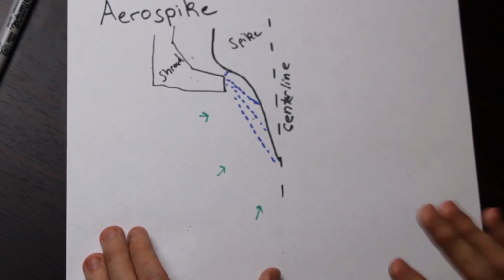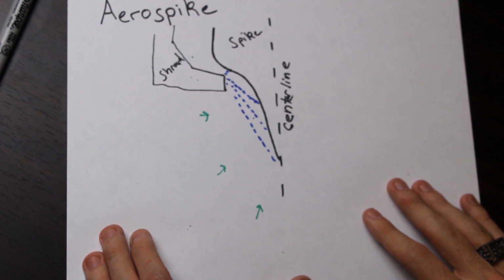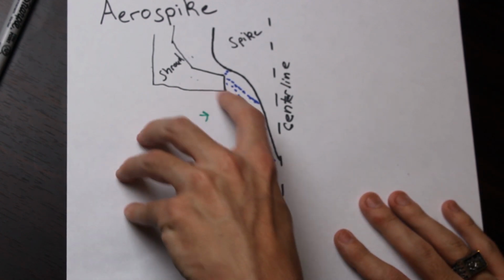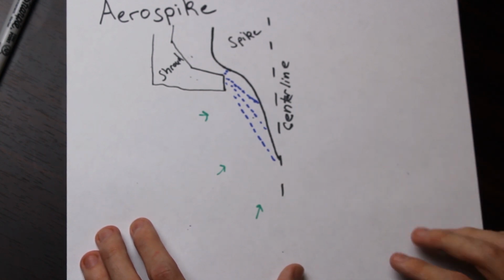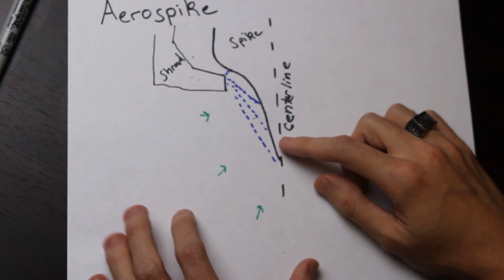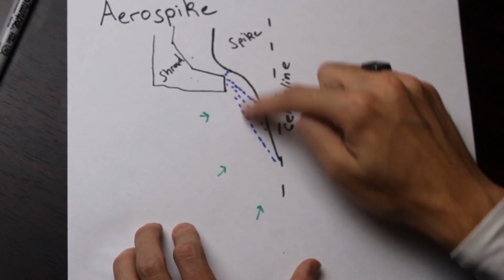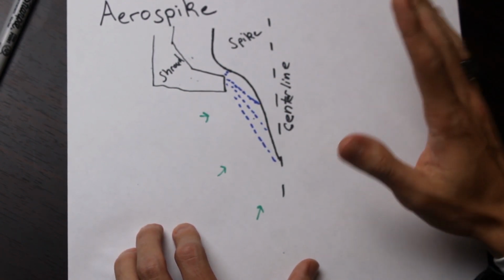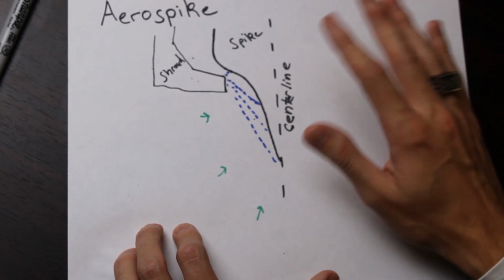So we've got a lot of concepts thrown out on the board here, so let's work through and figure out how we do this. The question is, how long do these Mach lines need to be, and where do they intercept the spike profile? At any point along the aerospike, if the gas were to leave the nozzle there, it would have some pressure based upon how much it had expanded up to that point. And this pressure ratio can be plugged into the isentropic flow relations to find out what the Mach number would be.